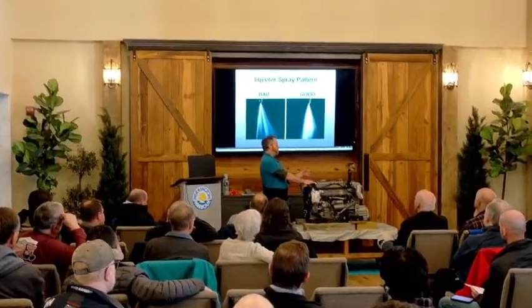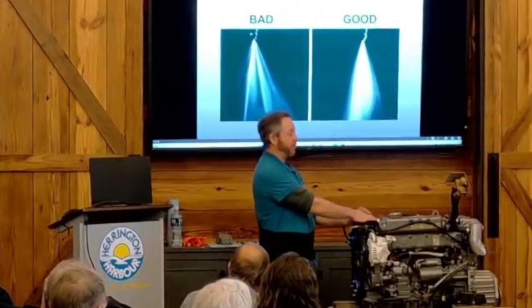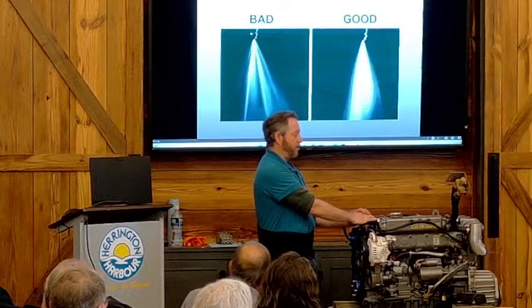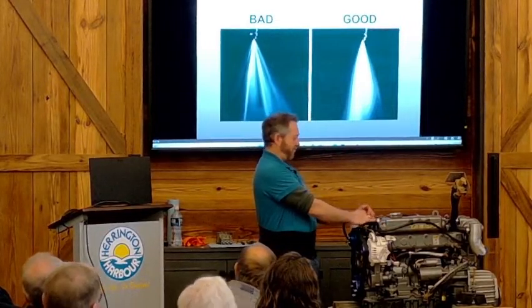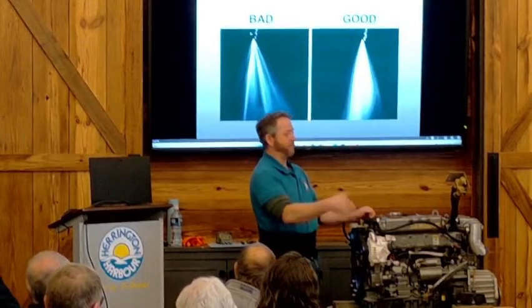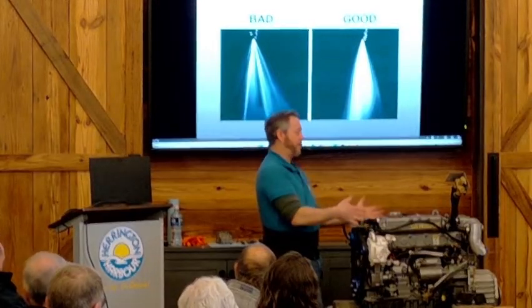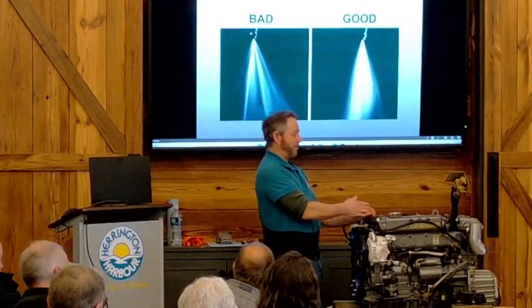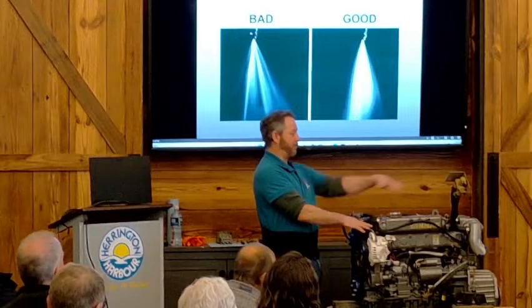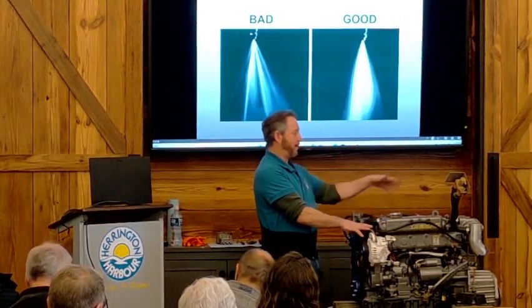Well, most manufacturers want to see you putting an 80% load on the engine or generator, doesn't matter which one it is. Now, if you hit your hull speed before that 80%, then you run it at hull speed. It's up to you to run it a little lighter. You're just not creating as much heat, so you're going to have a little bit more carboning on the valves and stuff.